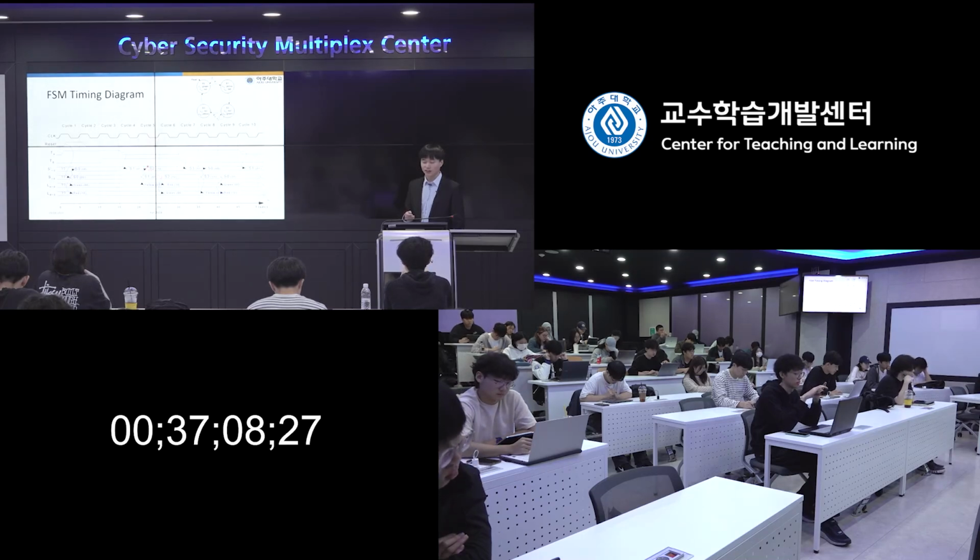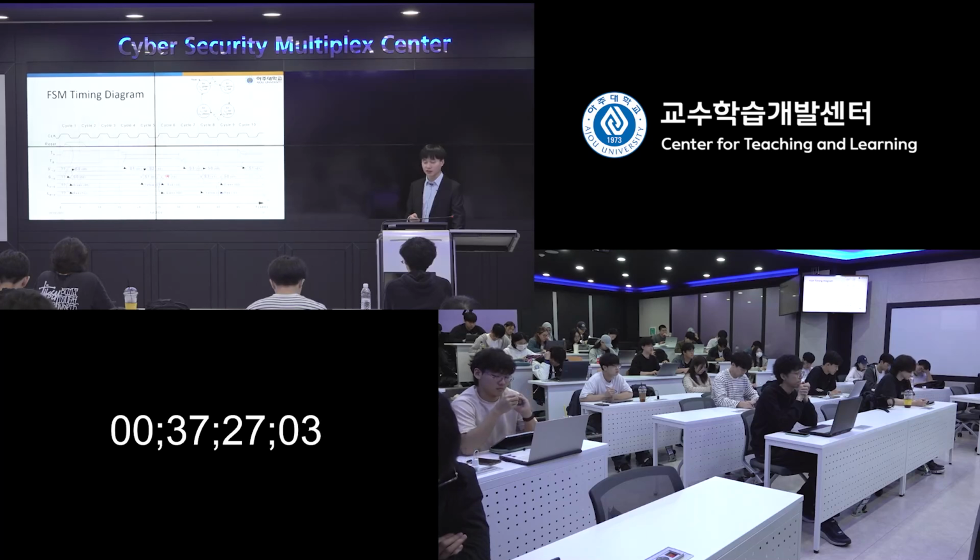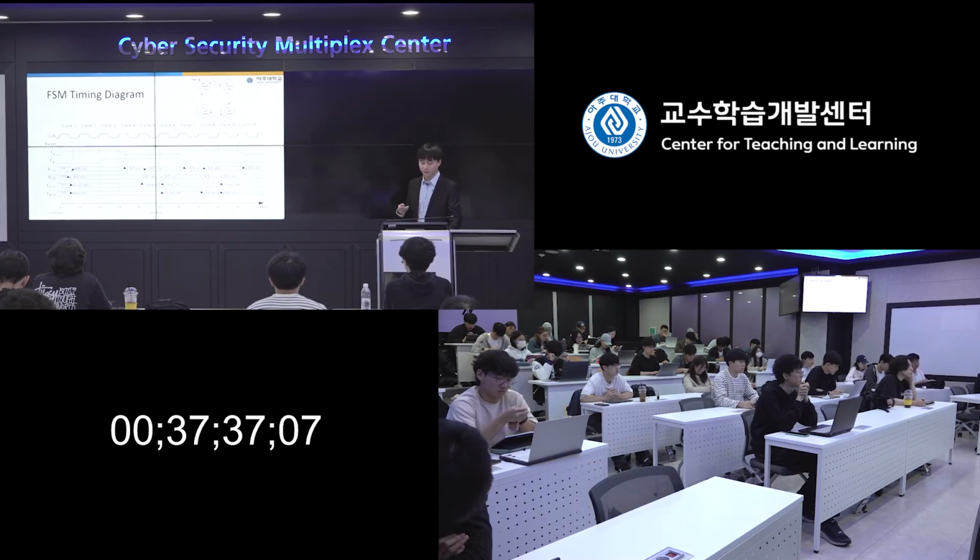This S2, from this time to the next cycle number 6, will be stored in the register, and that rising edge will be reflected at S2. Okay? So then the remaining is similar. You can just check once S2 is in the output, it will directly trigger the output control signal for the traffic light. Then trigger LA and LB to be red and green respectively.